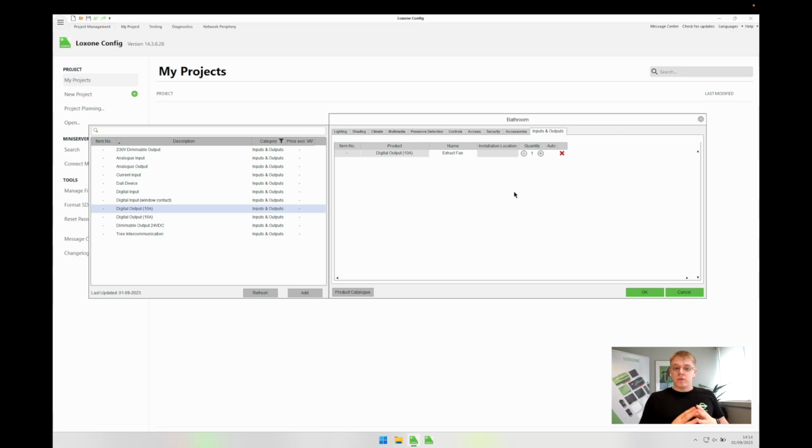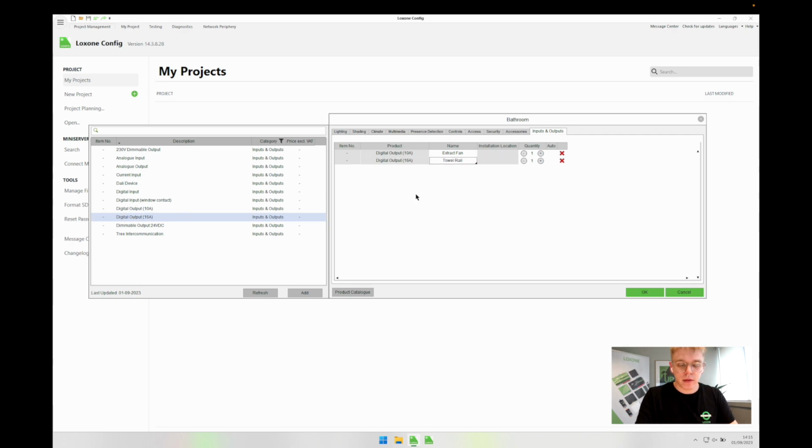And finally, for the bathroom, we've got wet underfloor heating, but I would like to add an electric towel rail for warming and drying the towels over the summer, of course, and the winter, but not going to be impacting the climate control of the room. So I'm going to add another relay, this time a 16 amp relay because it's potentially going to be a much higher load than some of the light fittings, and I'm going to name this the towel rail.